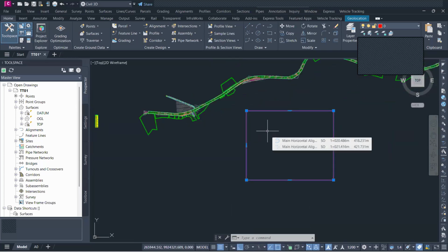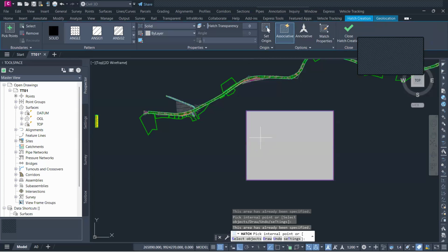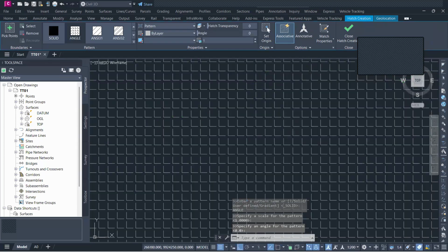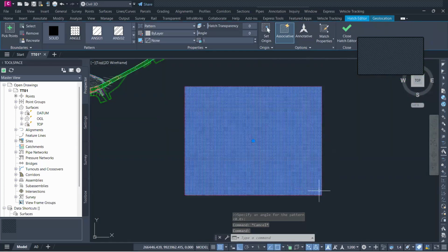the machine is your reference to make sure that you're getting the actual exact location. So you pick points along this entire section. So we will have entire points. And then once we pick that, we are going to import them in Civil 3D. And once we import them in Civil 3D, we are going to use the same method that we used to create a surface. So let's assume this is a surface. This surface will be representing the existing ground.